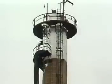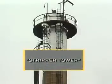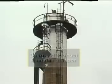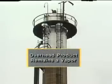Another type of tower is called a stripper tower because it strips lighter components out of the products. However, unlike most other distillation systems, a typical stripper tower system does not condense the overhead product into a liquid. Instead, the overhead product remains as a vapor and is sent for further processing.